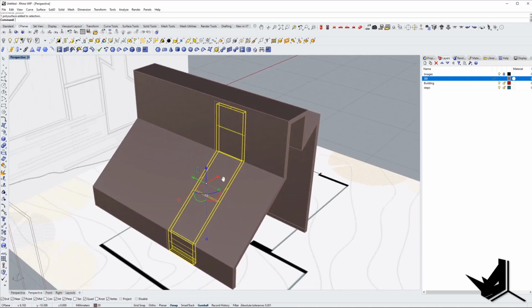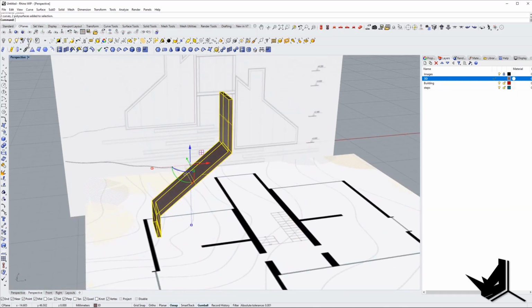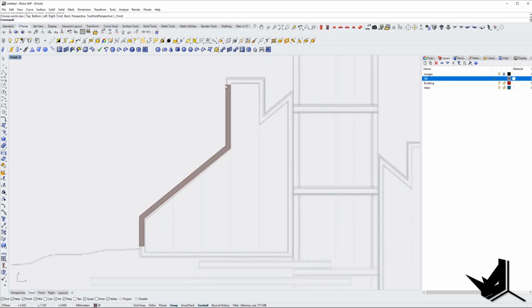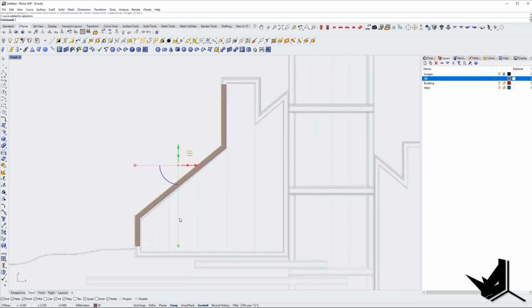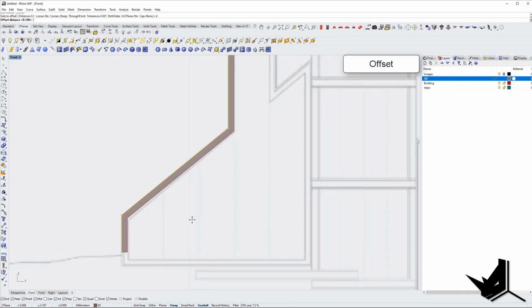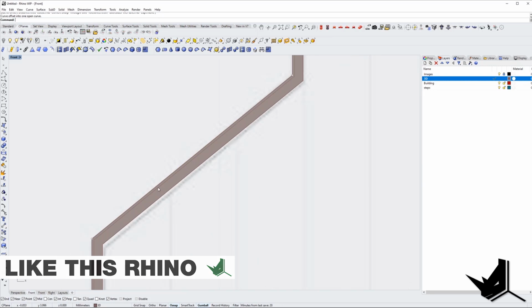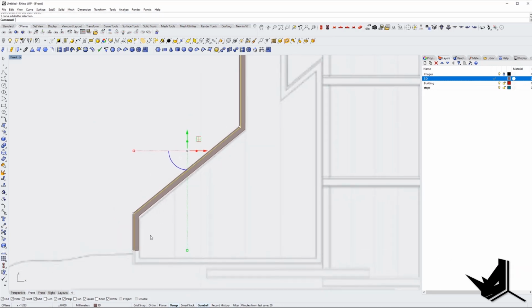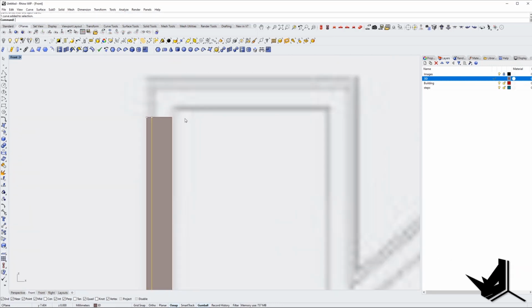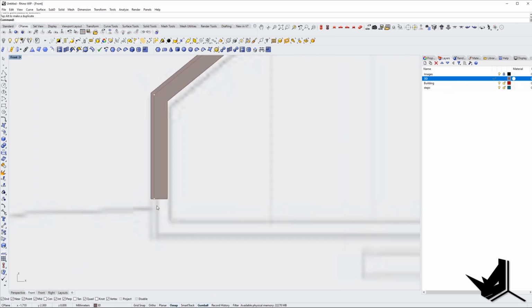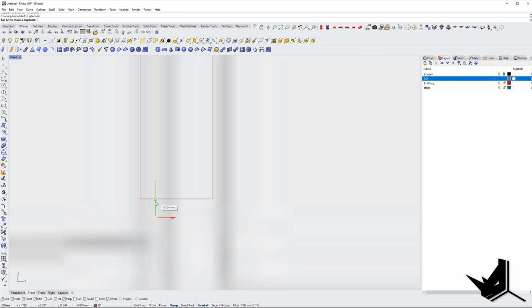And for example, if you want to create the thickness of the window, you can simply isolate this, and you can go ahead from this side, and let's create one line here. And we can do the offset of this line, for example, 0.03. And then we have this other line that we can use, and I'm gonna select this, extend it just a tiny bit here and here.